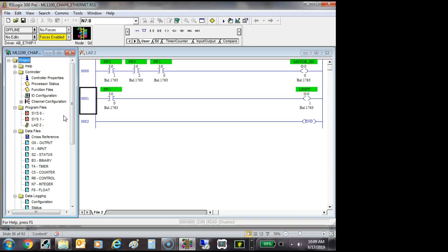System 0, that's what your book says: this is where the operating system is kept. This is what the PLC uses. They don't want you to get into it or change it. So really, it's like the end instruction. Why display the end instruction when you can't change anything? Newer versions of the RSLogix programs, the 5000, don't show the end instruction or the rung with the end instruction.